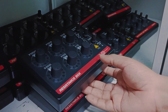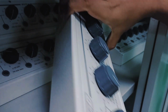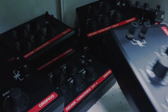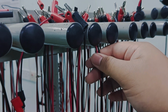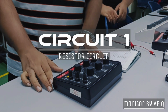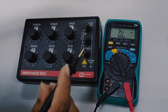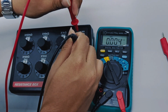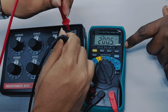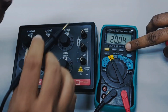Third day, we go to the lab to construct these 3 circuits. We take all the necessary material and tools for this project. In this circuit, we adjust the indicator resistor to 200 ohm. Now we turn the knob of the multimeter to ohm sign. Connect the probe of the multimeter to the legs of an indicator resistor. One probe will be on one side while the other one is connected to other side.